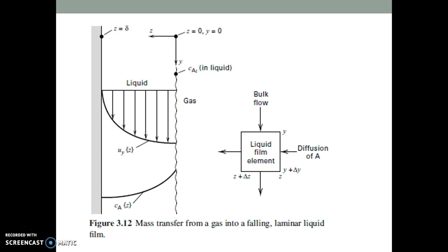In theory, it is not necessary to have an experimental mass transfer coefficient for laminar flow, since the equations of momentum transfer and diffusion can be solved. However, in many actual cases, it is difficult to describe mathematically the laminar flow for geometries such as flow past a cylinder or in a packed bed. So experimental mass transfer coefficients are often obtained and correlated.